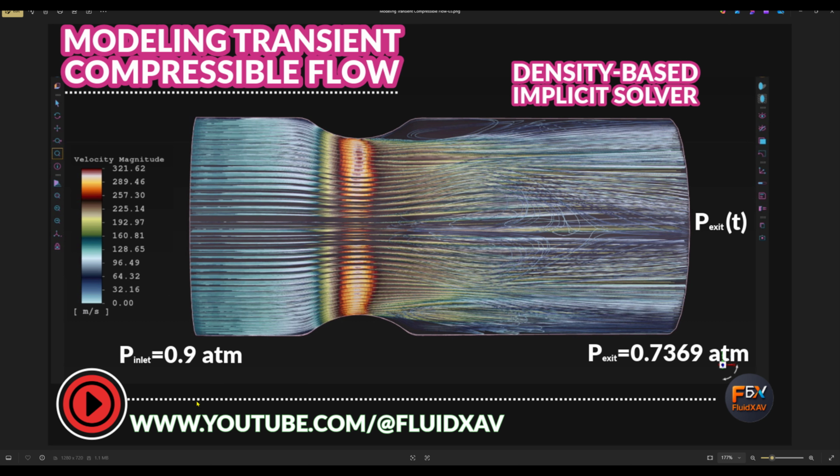The main boundary conditions are the inlet, which is a pressure inlet with 0.9 atmosphere total pressure, and the 0.7369 atmosphere as the initial static pressure. The outlet pressure is 0.7369 atmosphere, like the initial static pressure, and the walls are no slip walls, and symmetry will be applied along